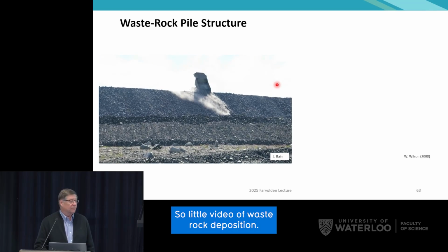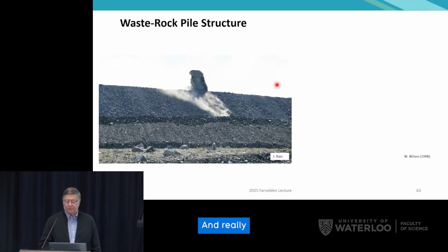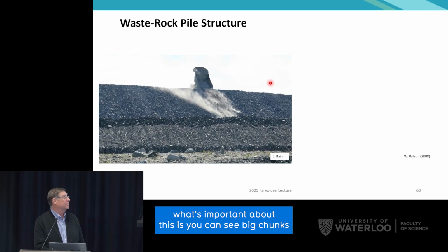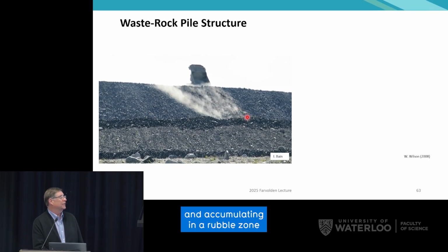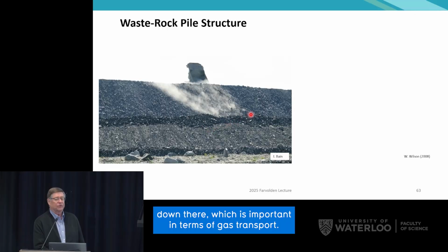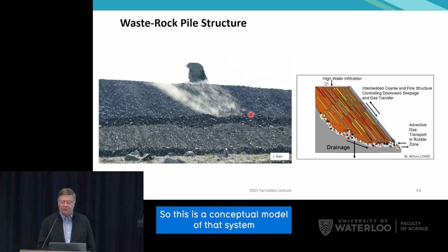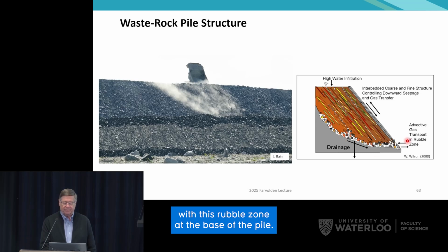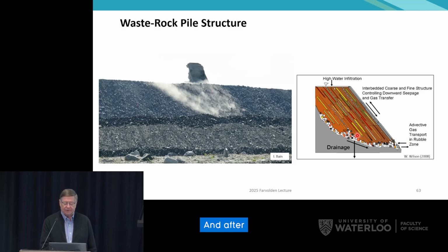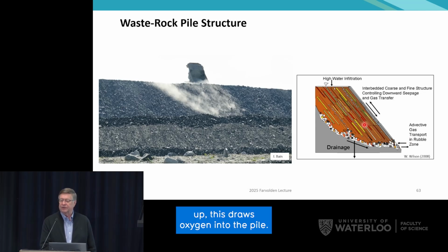So, a little video of waste rock deposition. And really what's important about this is you can see big chunks of rock rolling down to the base of the pile and accumulating in a rubble zone down there, which is important in terms of gas transport. So this is a conceptual model of that system that was developed by Ward Wilson from Alberta. And so you end up with this rubble zone at the base of the pile, and after sulfide oxidation gets started and things start to heat up, this draws oxygen into the pile, so much of the pile is oxidizing at the same time.